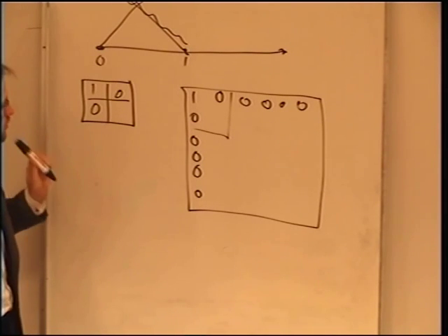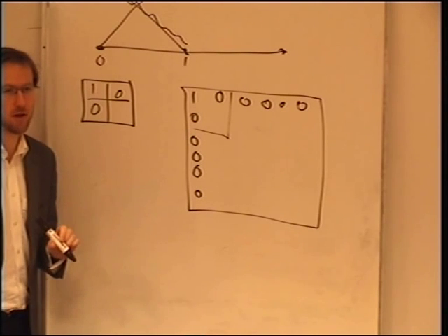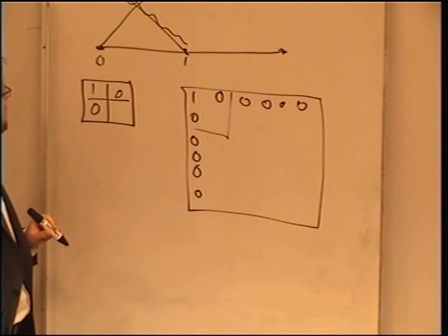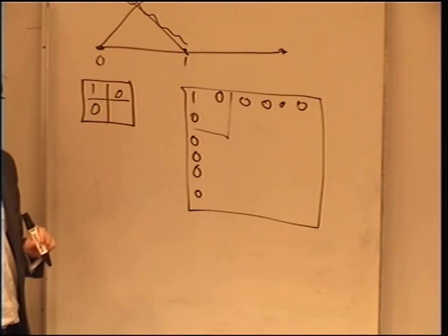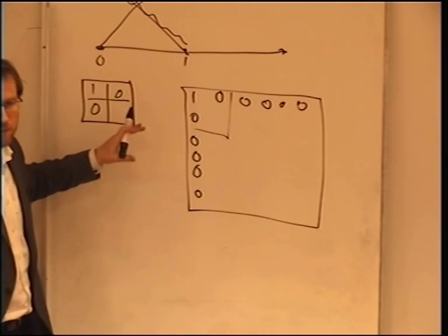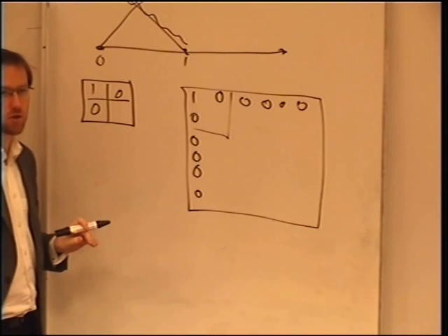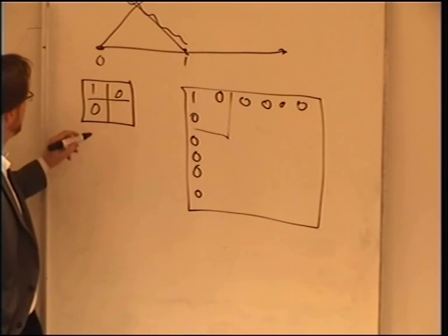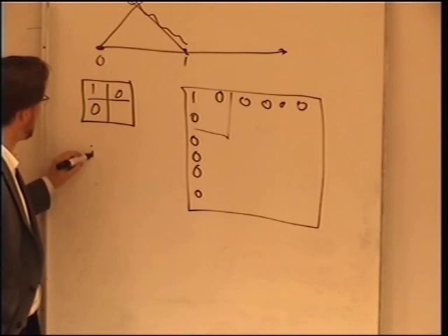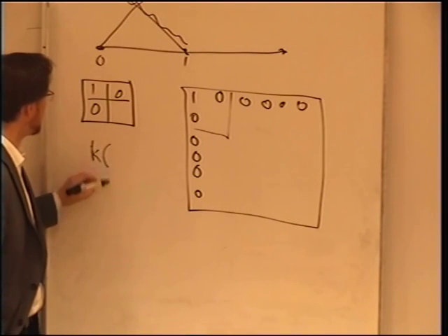The final option is what we do, which is we muck with the indirection map. When we know that we're assembling into a function space which has boundary conditions, where those boundary conditions apply, we change the indirection map. So if you look up, in this case, K is our indirection map, and K takes which element we're on.